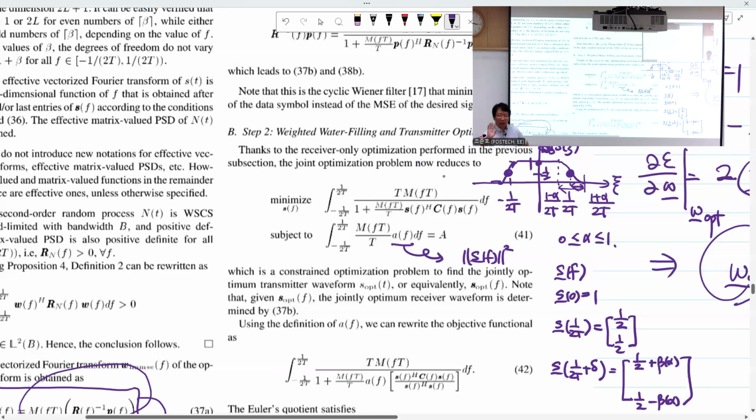Here, beta is not that excess bandwidth. It's some function of alpha, depending on, it would be cosine something, right? And you know that the raised cosine has point symmetry. So if you have an increase from 1/2, then you have the same decrease here in the value, right? Something like this.